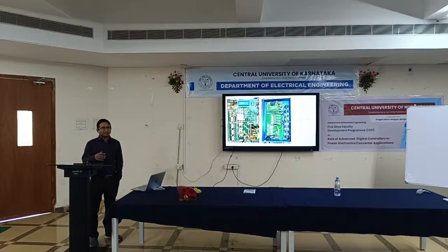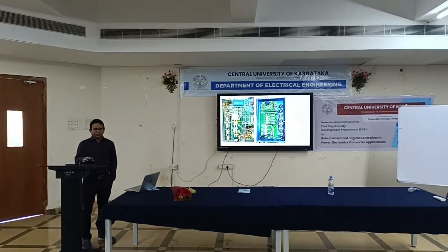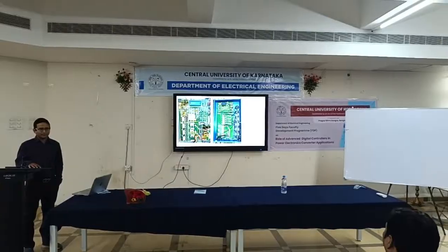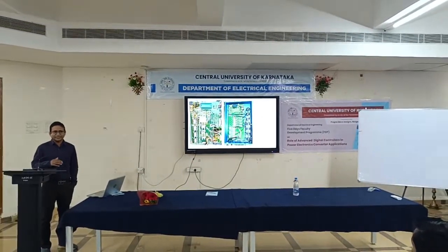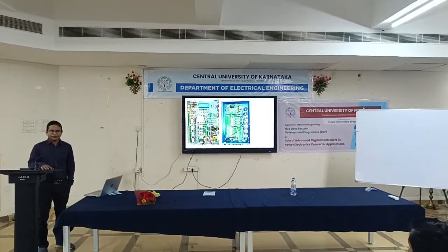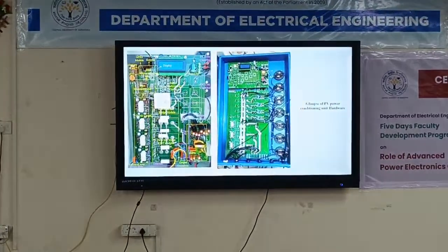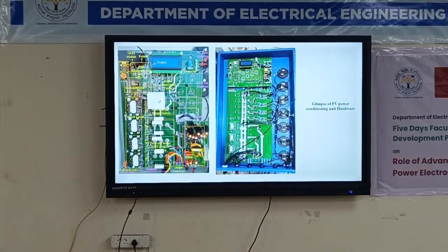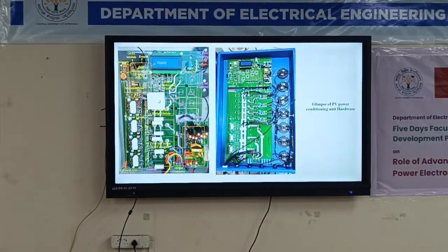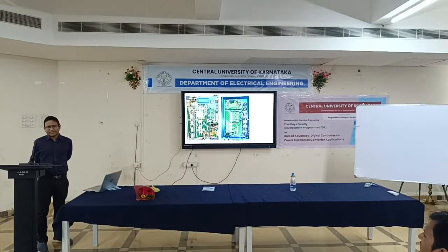But for power converters of high rating and a bit more challenging power converters, it's very difficult to achieve closed loop control using analog control, like operational amplifiers. It's one way of achieving system control, but that is outdated technology. We use modern, highly versatile microcontrollers, which are general purpose microcontrollers, where we code our control strategy. So we have feedback and we have the outgoing signal PWM, and the HMI, or human machine interface.